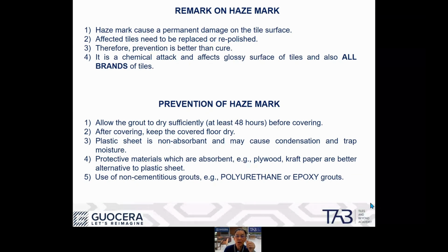If you can't, then we have to go for a more expensive alternative. If you use polyurethane and epoxy grout, you can have water ponding, whatever. There's no issue because there's no reaction. Water will not react. There's no calcium oxide in polyurethane and epoxy. So you can allow the water to splash in from the open windows for 3 months, 4 months, no problem. Haze mark will not occur.